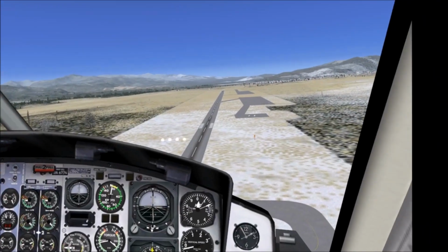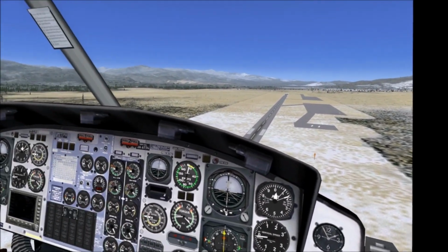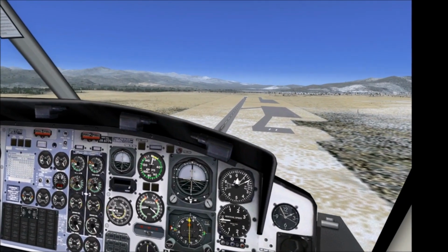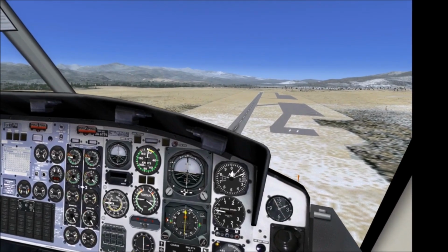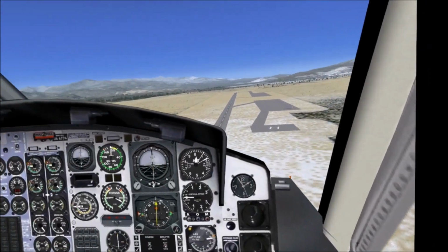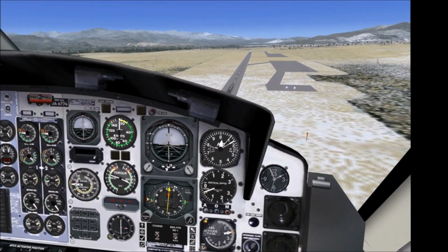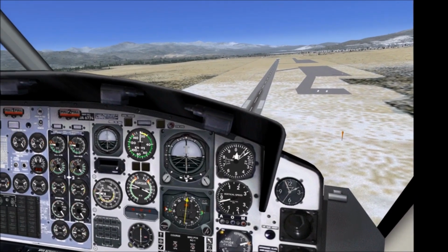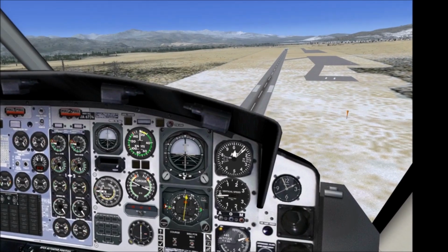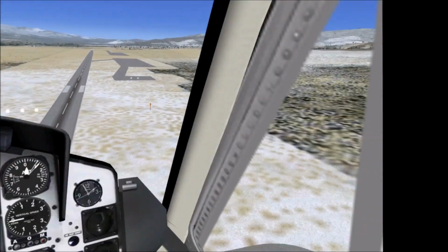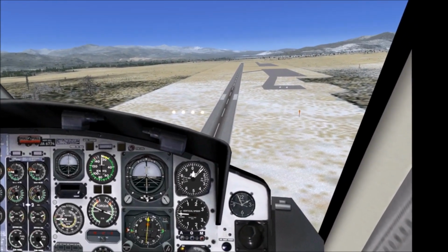Airspeed dropped off a little bit more than I would have liked, but I'm already seeing the problem we're going to have here. So I'm going to zero out the airspeed just to see what's going on. And just as I suspected, we have OGE hover power, like a lot of it. Oh, maybe not. Bringing in that power. Okay, maybe we don't. Nope, looks like we don't have a huge power margin, but we do have OGE power.